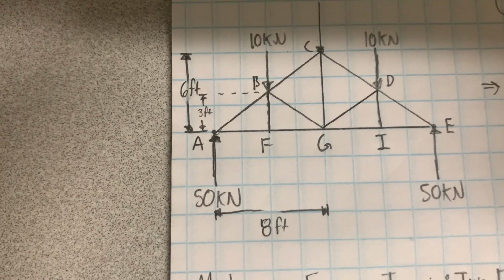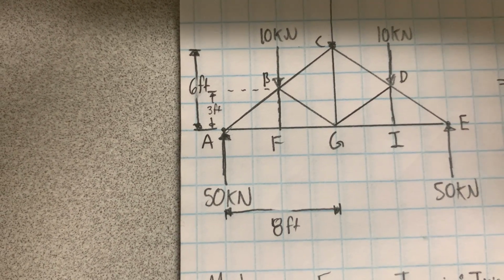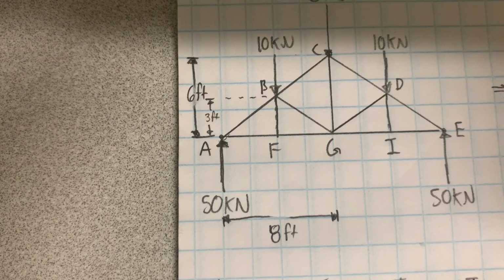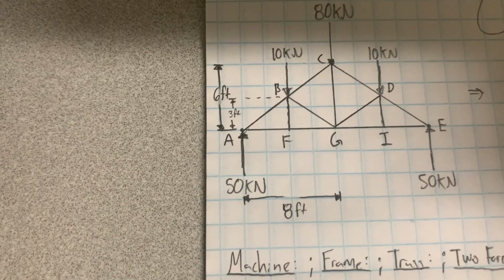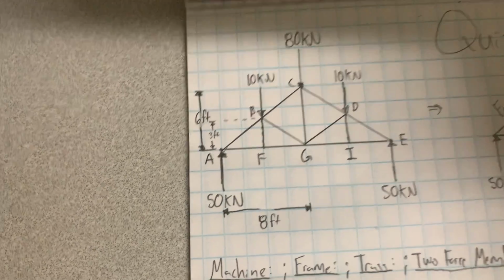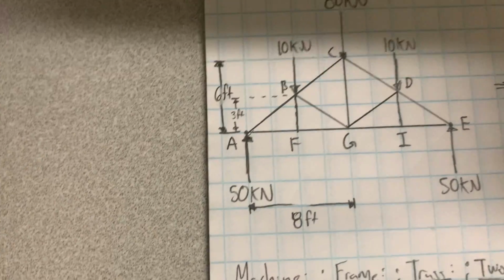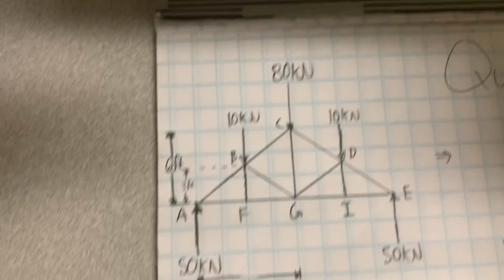A two-force member is a structure that has two points where external forces can be applied, and they are on the same line of action. And members with pins at two ends have no other forces.